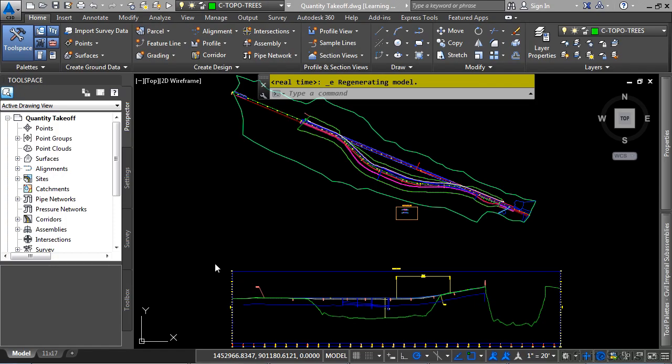You can add quantities to your drawings using Civil 3D's QTO Manager to apply pay items to AutoCAD Civil 3D objects or regular AutoCAD objects. Incorporating pay item information correctly into design plans, including plan sheets, summaries, and bid documents, is a major task for designers. You can use the QTO Manager functionality to automate the pay item process to reduce those errors.